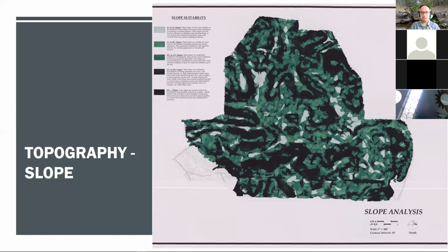But again, stabilization and erosion controls may also still be required on medium to steep slopes, 8 to 15%. That's a rather moderate slope. You would need to consider soil stabilization and erosion controls there.